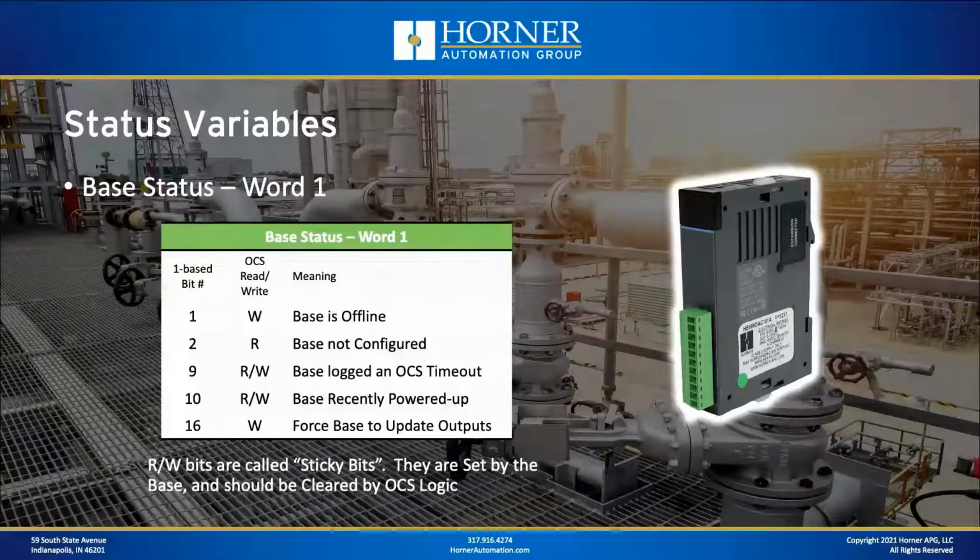Also, there's a bit that says the base at some point has logged a timeout from the OCS. What does that mean? Let's say that for some reason the OCS was powered down while the base was powered up. They were talking originally, but when the OCS powered down, suddenly the base got a timeout.